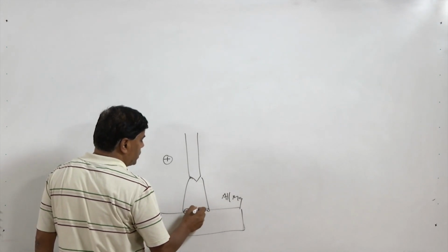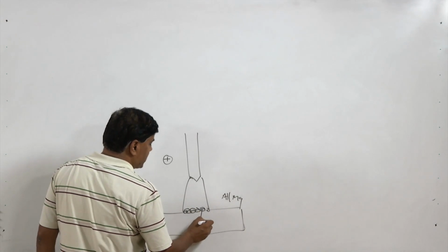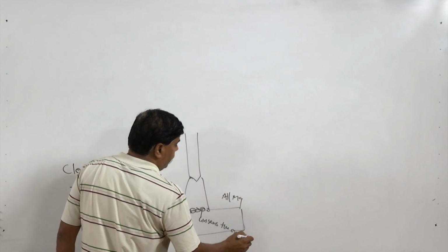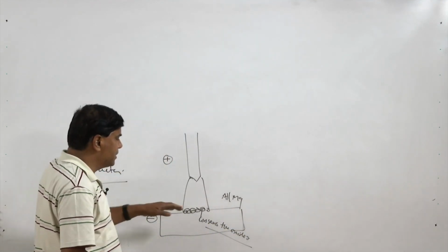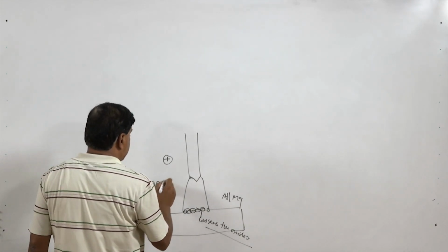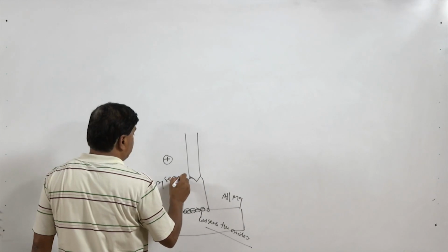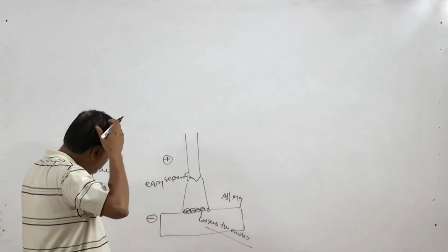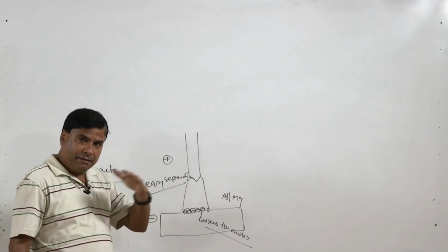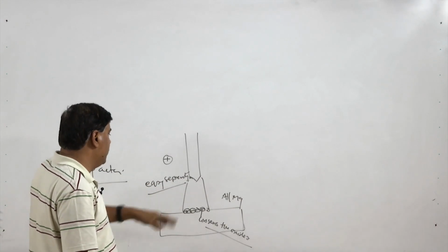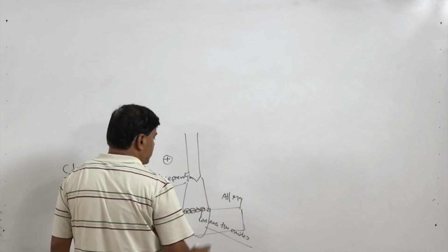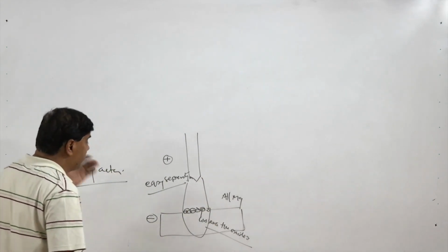So, mobile cathode spot formation actually loosens the oxides being formed. This loosening of the oxides due to the mobile cathode spot helps in easy separation from the molten metal, and because of this these oxides start getting floated over the surface of the weld pool, so they can be separated easily. This is the advantage of using the polarity favorably.